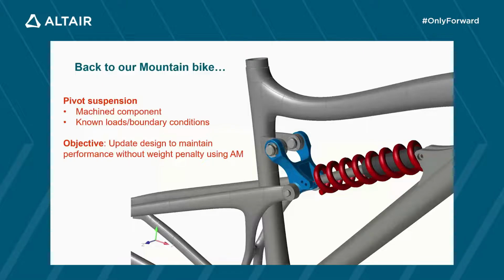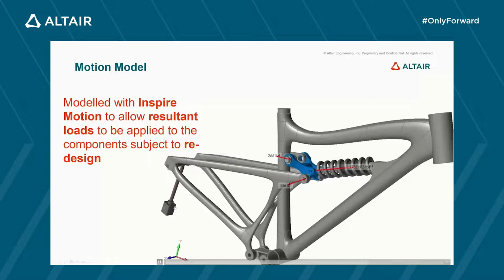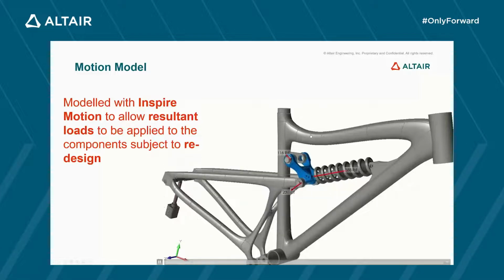Now, the first step using Inspire is to generate a motion model. Now, this helps us assess the resultant loads applied to the component and allows us to redesign using these loads. So you'll notice here, we've created this placement force on the rear axle. We have this mechanism causing our pivot suspension arm to react.